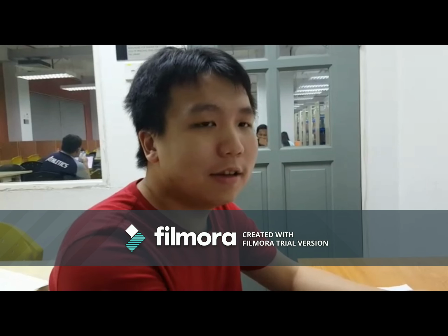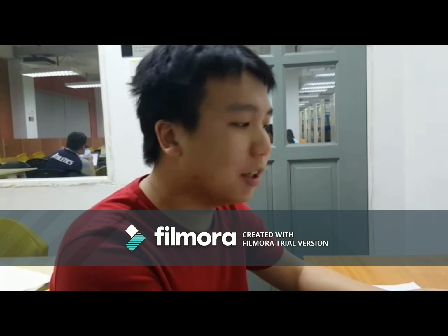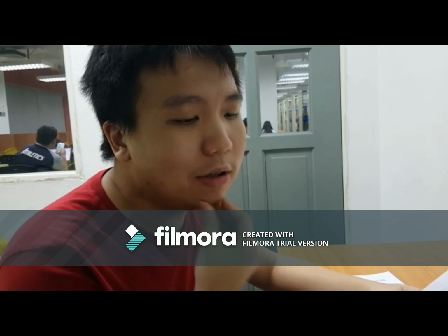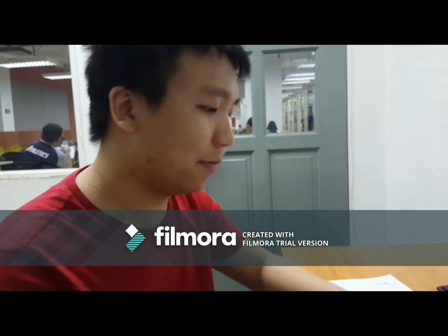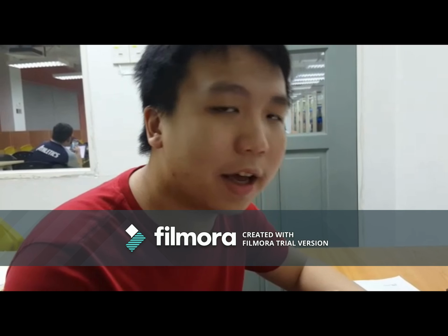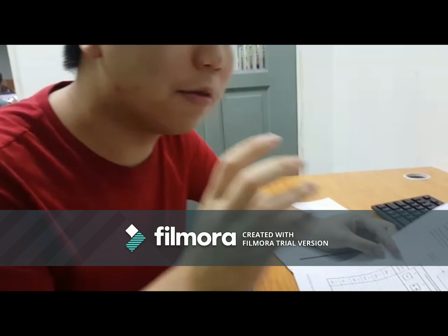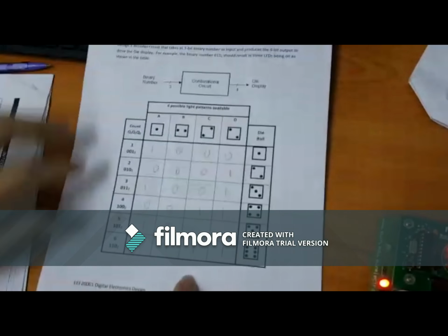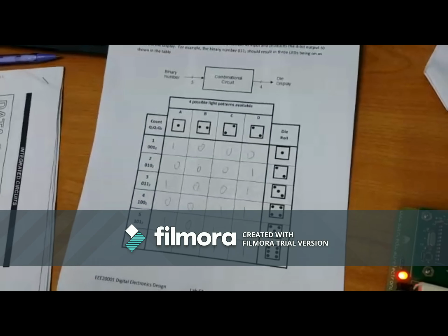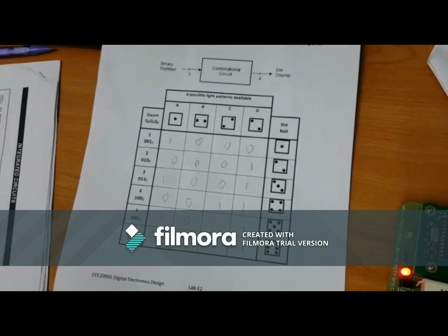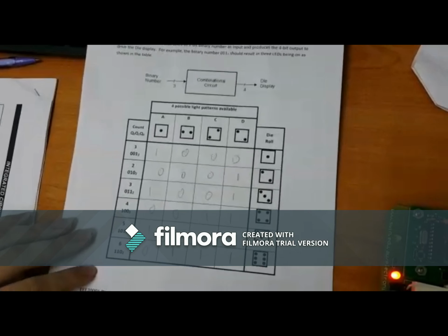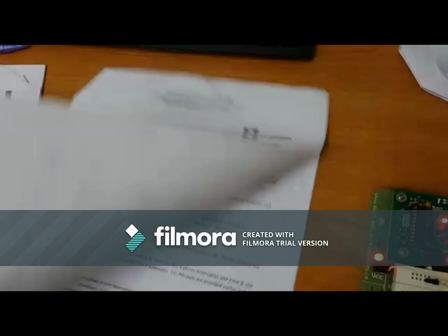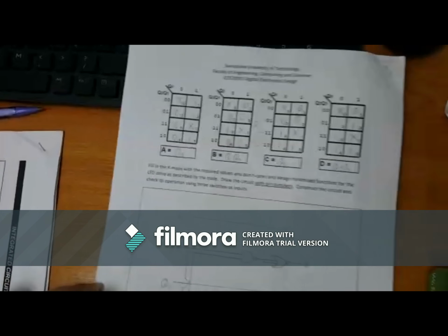So this is part 4 and 5 together. This is basically part 3, but instead of using the LED to count from 1 to 6, we use the die module. This is the K-map of the combination of 4 possible light patterns to count from 1 to 6. These are the results, and then we have simplified it into the truth table.